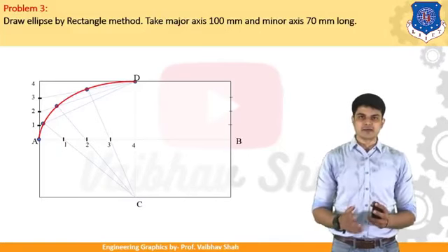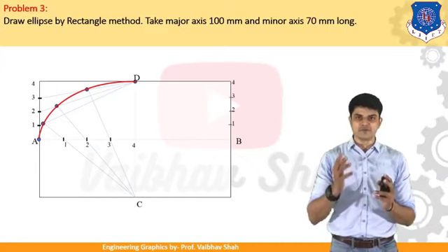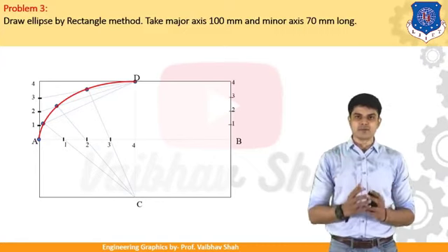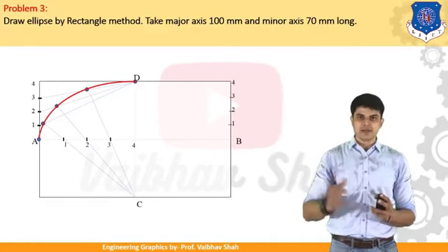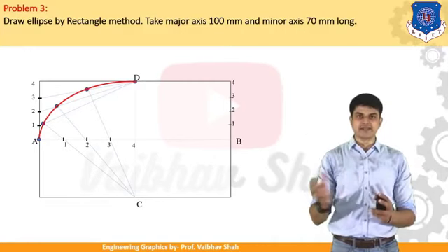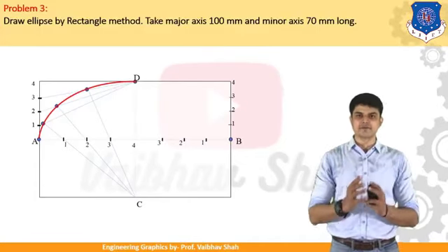So now we have taken the vertical line divided into 4 equal parts. So let us give numbering 1, 2, 3, 4. Always we are starting from the lower bottom point, from your point B, as 0. So 1, 2, 3 and 4. Then what we need to do is divide the horizontal line into 4 parts. We have divided the horizontal line also into 4 equal parts.